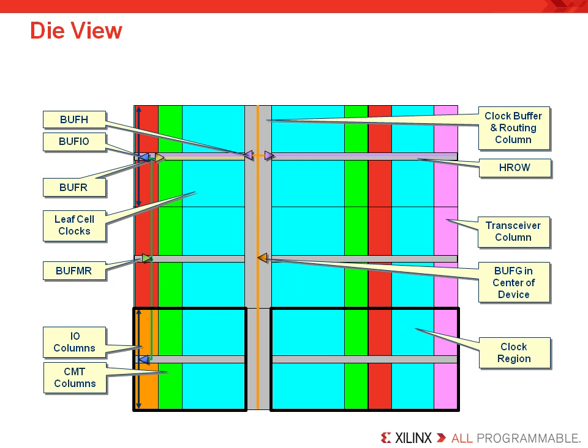This is the narrow line towards the middle. This is so an equal number of CLBs are placed above and below the horizontal routing, commonly called the H rows, and as I mentioned, shown as that thinner gray line. Each H row has a fixed number of BUFH buffers, and depending on your device density, you'll have a precise number of fixed clock regions on your die.